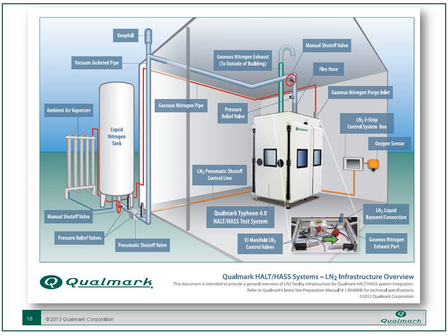We have two valves actually, one for a main on-off valve, a redundant safety valve when we're shut off, and another that does the actual proportional control of the liquid nitrogen into the chamber. And you'll also see indicated here the other thing we'll talk about, which is the vent for the chamber. All that liquid's coming in, we have to be able to vent the nitrogen gas out.